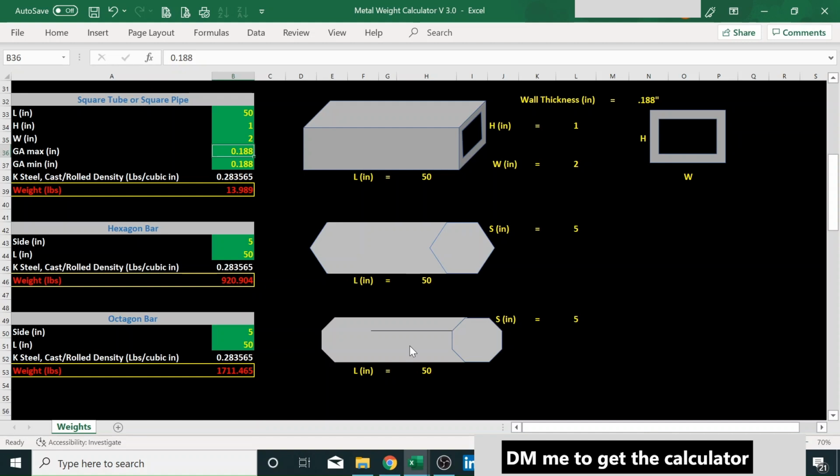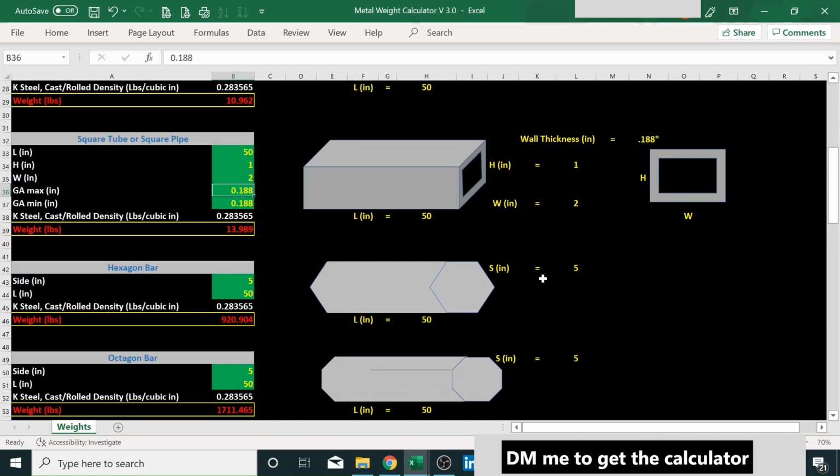I don't want to go through them here, but you can check them online. That's your homework. Basically, through those formulas, you get the volume of these bars. And again, you have the volume in inches, so you multiply by the constant weight of that metal. In this case, we continue with steel. Same thing with the octagon. And I again did a little bit of visual here, so you know what you're inputting.